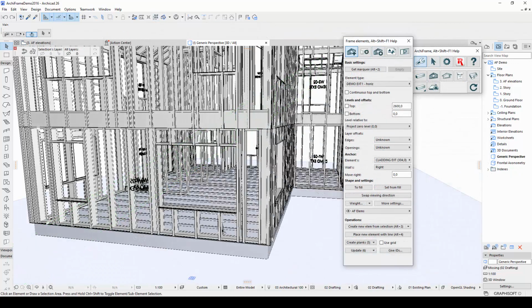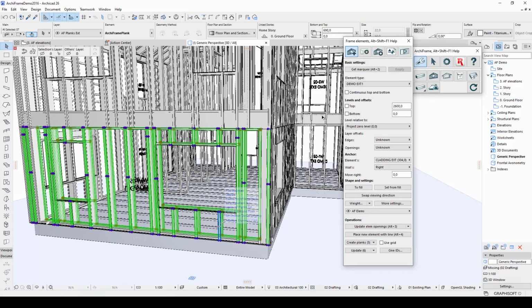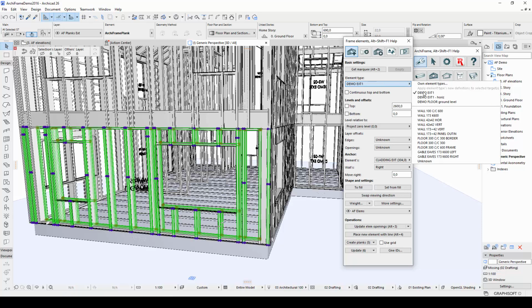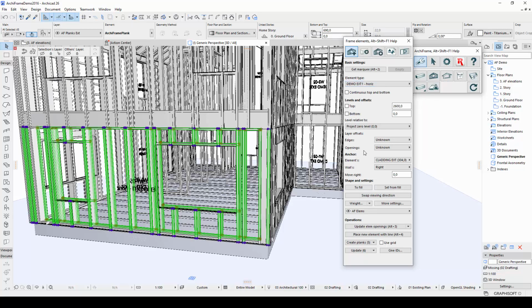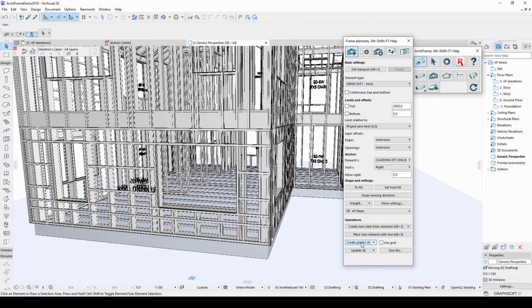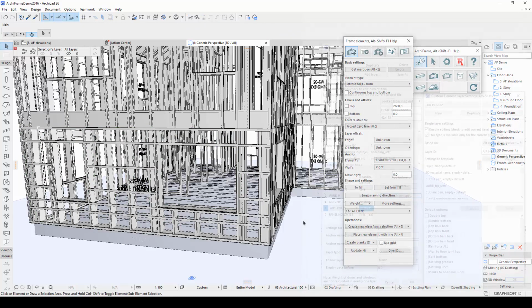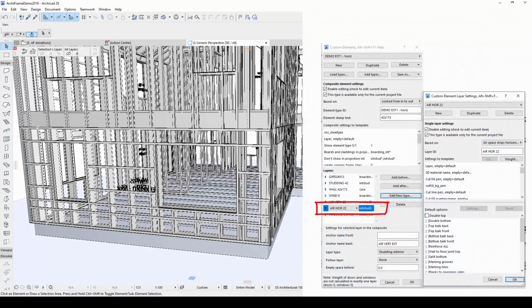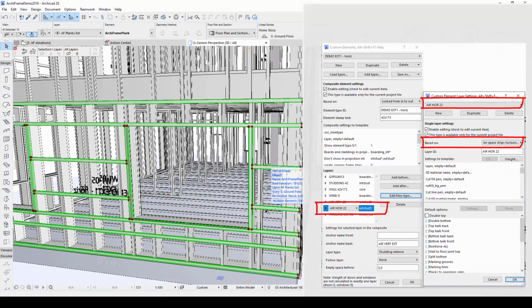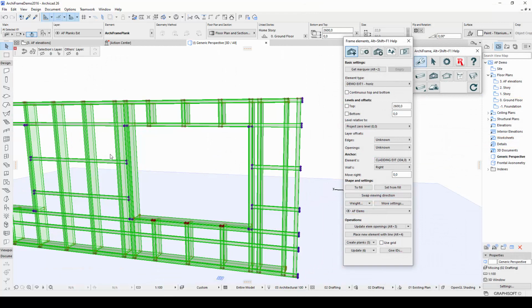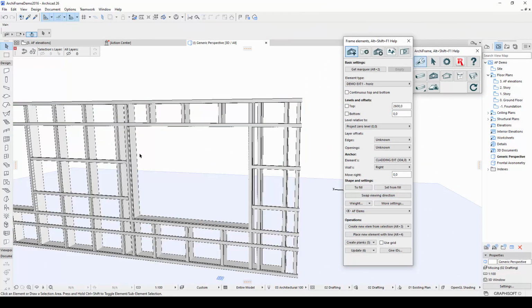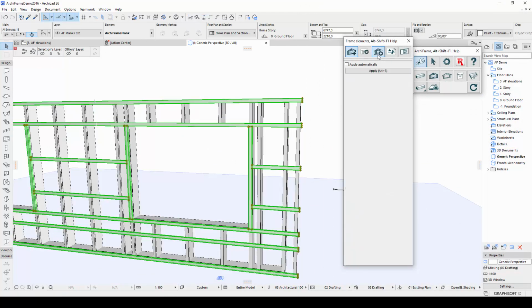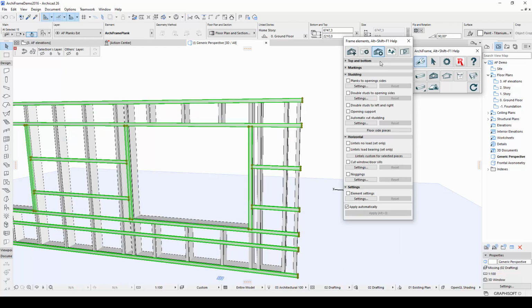Now let's move on to the fourth new element option, allowing you to automatically cut studding. I will update one of my walls so that it has horizontal studding and recreate planks. You can see my new wall definition here. Then I will select the new horizontal studding and open the Set Element Options tab in the Element Tools.